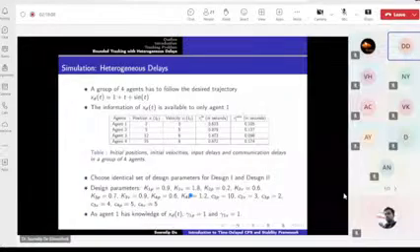The basic rule of thumb is that don't go for values which are very marginal, I mean on the verge of instability. If you are taking some estimator gain or controller gain like that, you will see that the system is stable, but it will be marginal, so choose in between, let's say, 0 and that particular threshold. And for agent 1, which has the information of the design trajectory, we just select the gains like this, gamma 1p and gamma 1b.